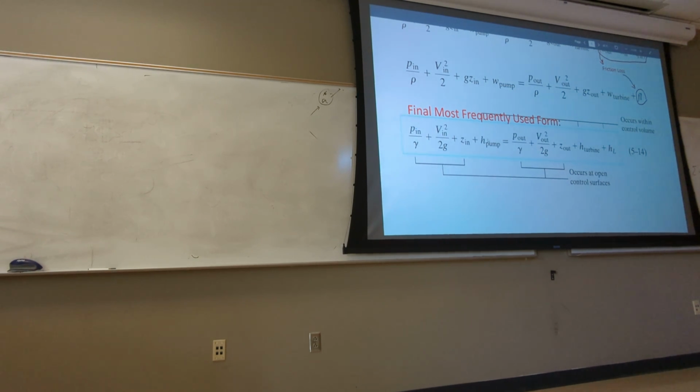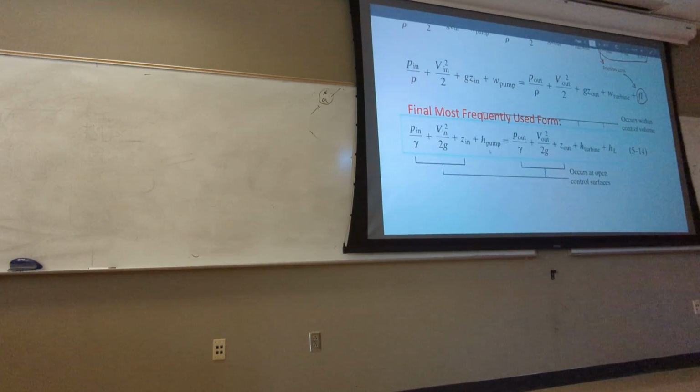We said that if you have frictionless and all those assumptions we had before, you get rid of this H, the head from the loss, the turbine, the pump, and then you get our Bernoulli equation back. But look, this is even more comprehensive than the Bernoulli we derived from the momentum equation, because when we derived it, we made the assumption that we integrate over the streamlines. We've got to find the streamline between 2 points, right? And if we change the streamline, that means if we change 2 points, the constant of integration will change, C1, C2. So we had a lot of limitation.